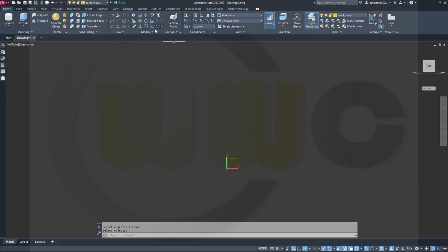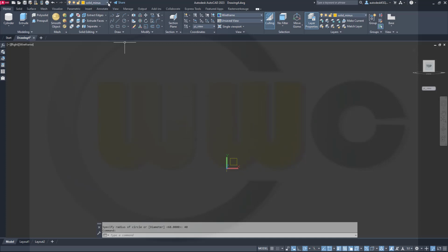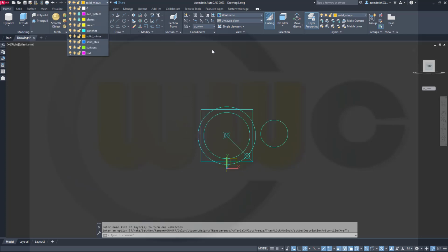Right click, and I need a circle, and that circle should be positioned at 140,103. And the diameter would be 40, not 80, but the radius would be 40. Yes. And let's move that to the sketch layer. Yes, it's hidden, I know. So bring that sketch back.